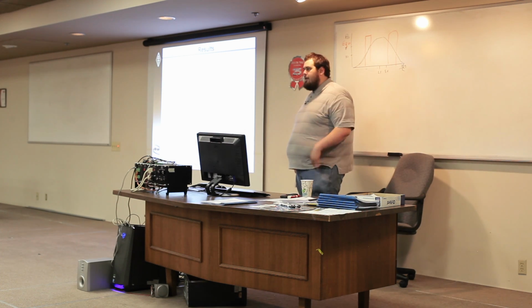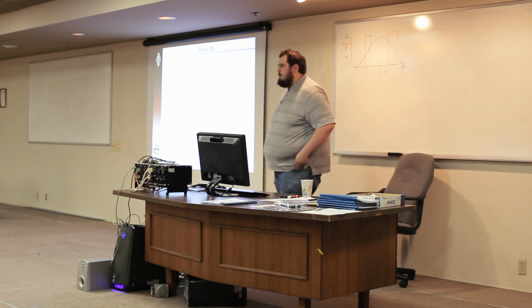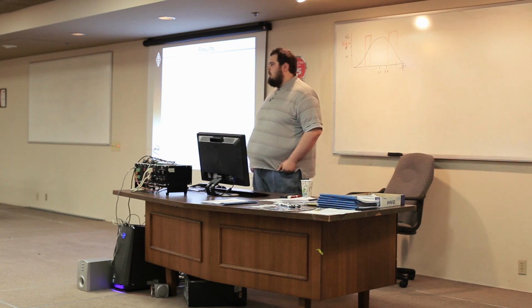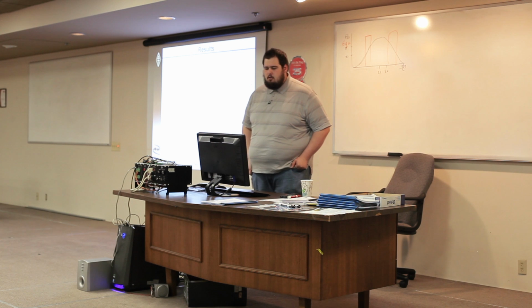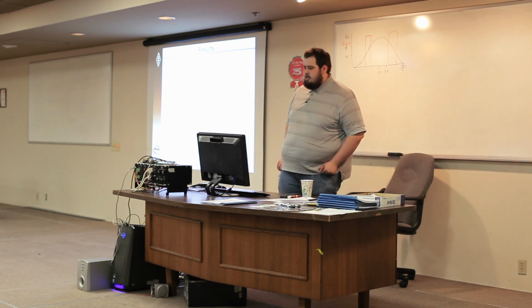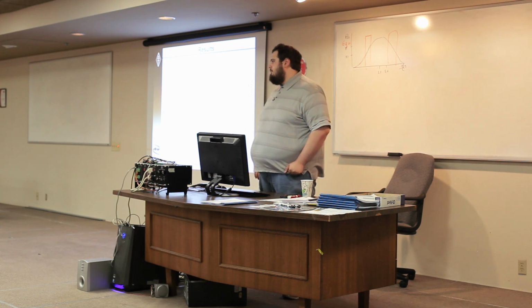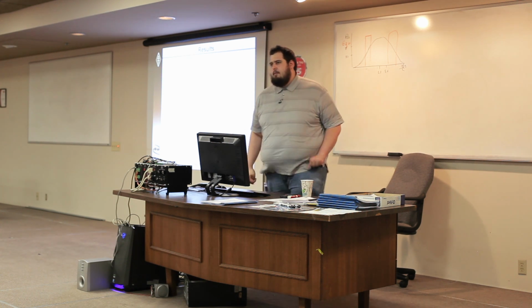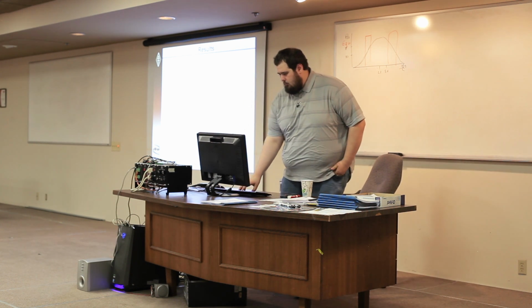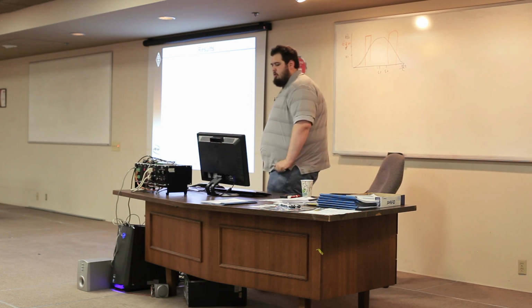But it should look similar to this graph I drew up here, where it increases over a span roughly equal to 5 seconds, a little bit over it, turning the EQU output high in the middle of that, and then waits a half second, then decreases again over a span of 5.1 seconds with the EQU output changing in the middle of it. So your plot, if you plot it, should look something like this one here. That's how you set it up for a single pulse.